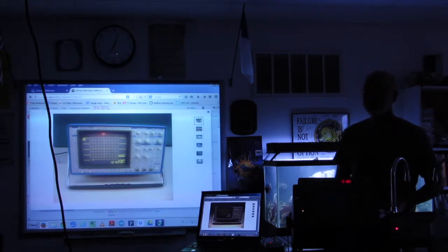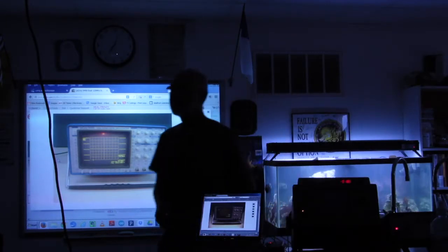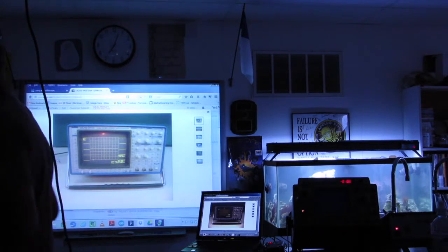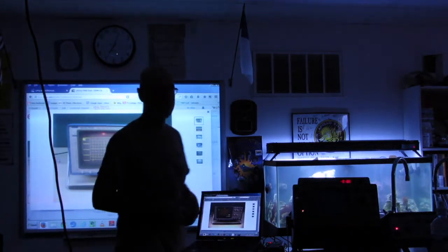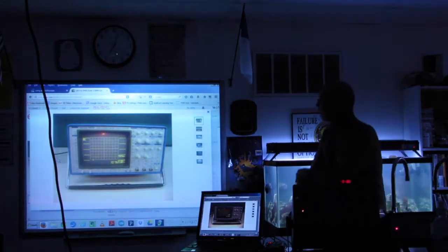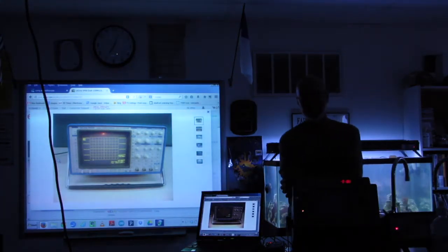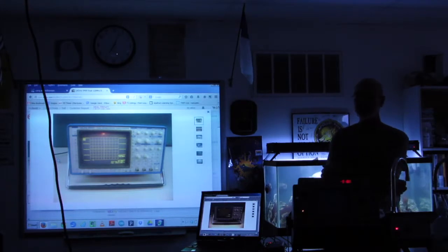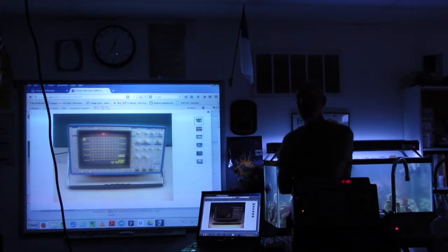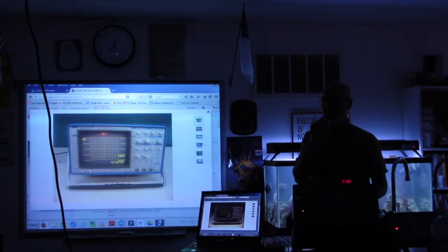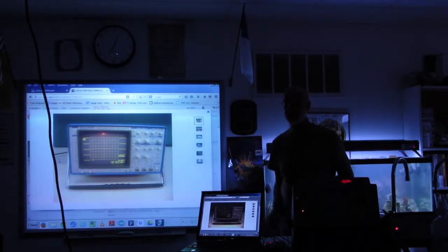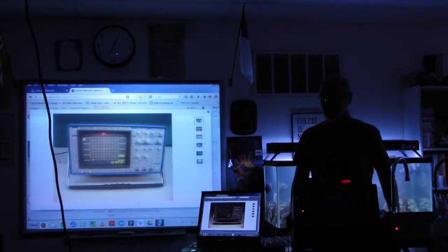Is there any difference in terms of what it's capturing between analog and digital, in terms of the exactness, if I could use that word? That's a great question. There is a difference. With an analog scope, you're seeing exactly the voltage that's coming in because it's analog. There's no conversion. No matter what you do to the probe, you'll see a little bit of something on the screen, and that's because there's a little bit of something going on at the end of the probe.